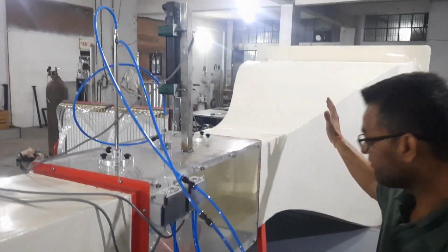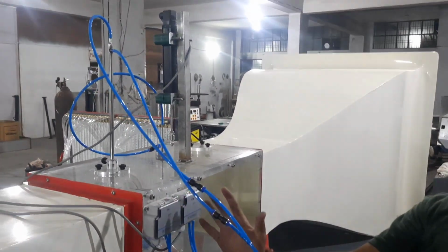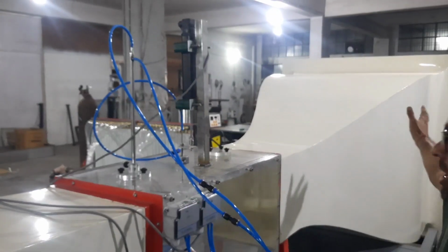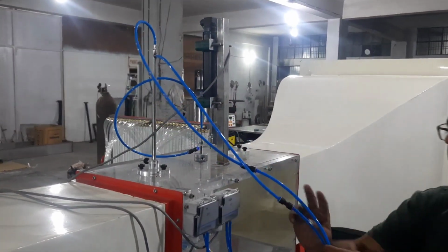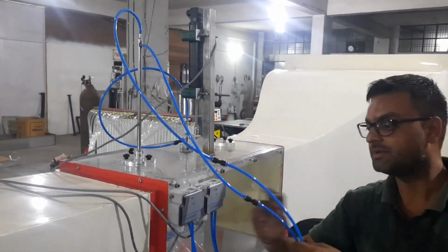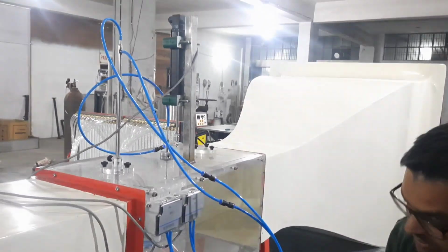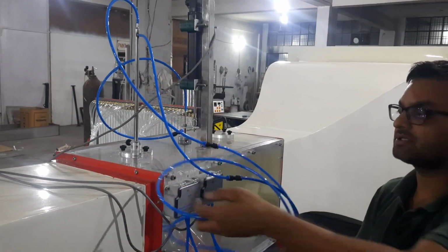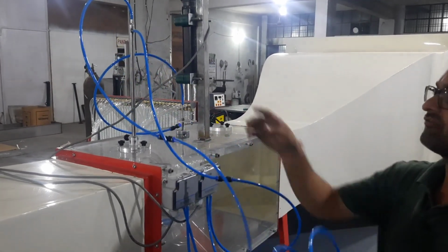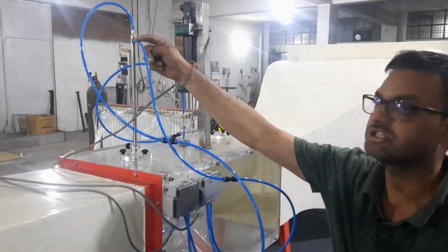Then when the air is drawn from the suction side, you will get the two pressures and their difference, and that differential pressure is calibrated to give you the velocity in meters per second. Similarly, if you connect these 2 points to the pressure transmitter that is calibrated in pascals, you will get the difference of the pressure between the total and the static.